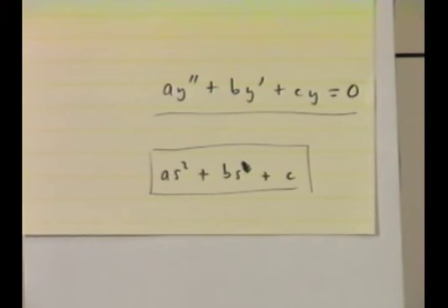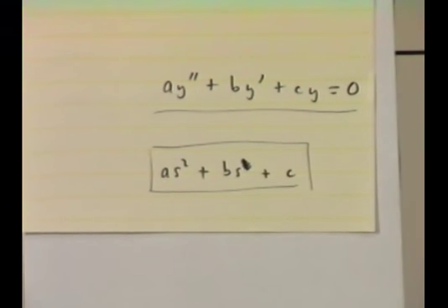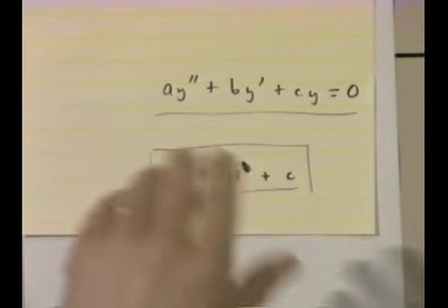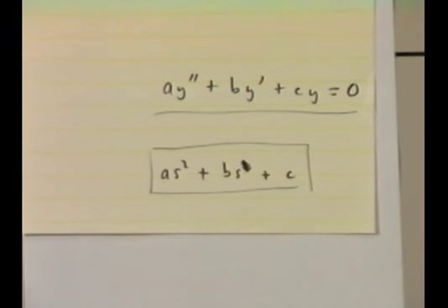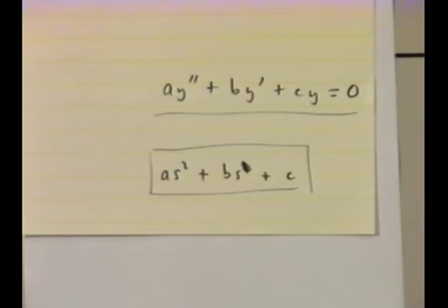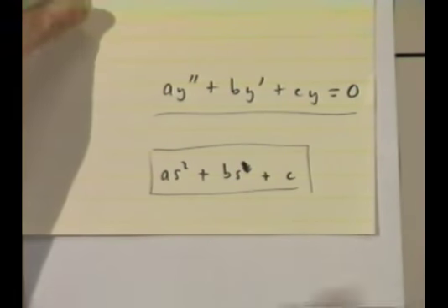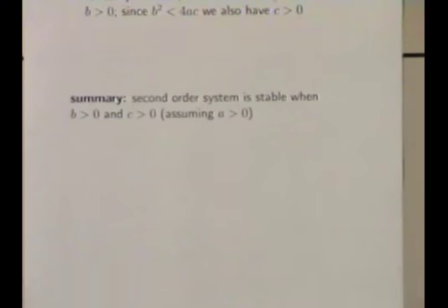It could be two real exponentials decaying with time. It could have a t e to the minus something t type of solution. It could be an oscillation. To actually calculate which of those it is, you'd have to solve a quadratic, and then you would know. Are we talking about a fast oscillation with a slow decay to 0, or something that does 2 cycles and decays to 0, or this kind of thing, or no cycles? That's the idea. Okay.